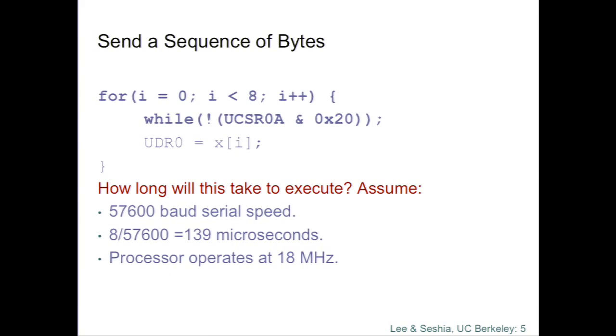And we did the calculation last time about how long it takes to execute, assuming the fastest RS-232 line, which is 57.6 kilobaud. And we discovered that each iteration around the while loop takes 2,500 processor cycles. Okay? So it's a lot of cycles where you're not doing anything interesting in the processor. You're just waiting for the hardware to be ready.